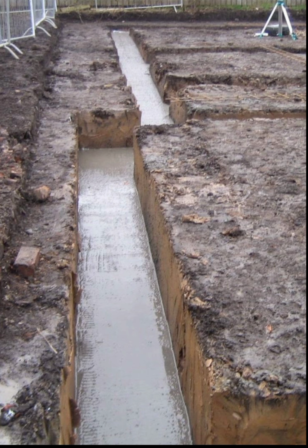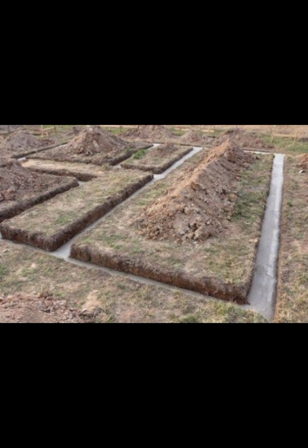They can also be used when you are using closely spaced columns. You can use a strip foundation. They are commonly used for low-rise buildings with low bearing walls and in conditions where the soil has adequate bearing capacity. So how is it constructed?